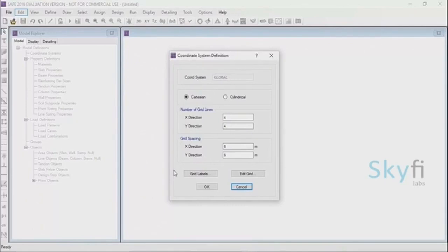You will first draw the slab of the building plan, and then extend equally on all sides to make the footing. The building slab is of 18 by 18 m dimension. Note that you will draw the building slab of 18 meters by 18 meters dimension with the grid. You will then extend it for the mat footing slab later. Thus, using 1 meter spaced grid lines, you will need 19 grid lines in both X and Y directions. Thus, for both X and Y, enter number of grid lines as 19, and spacing as 1 meter.